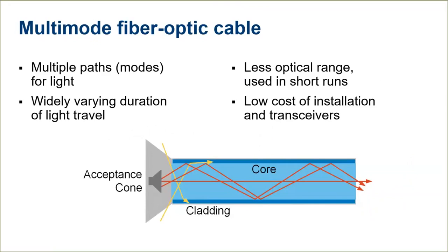Because the light can take many paths of a variety of lengths, not all the light from the pulse reaches the far end of the fiber at the same time. This lengthening of the pulse duration is part of what is known as modal dispersion. So significant dead time must be allowed between the light pulses to allow all light to reach the opposite end of the fiber. This, of course, limits the attainable bandwidth of a multimode fiber.